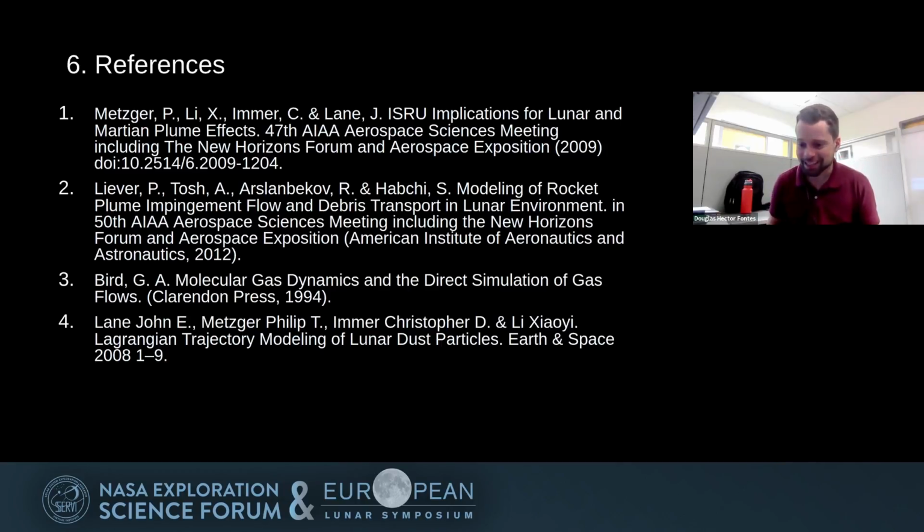I removed some slides because of the time, but yes, I used the DSMC code to solve the rocket plume flow. And in terms of the boundary conditions, we had a wall surface on the bottom surface and symmetry planes for the quarter domain of this 3D numerical domain. And to represent this near vacuum condition, we had a high speed velocity in the outlet flow of the radial outer surface of the numerical domain.